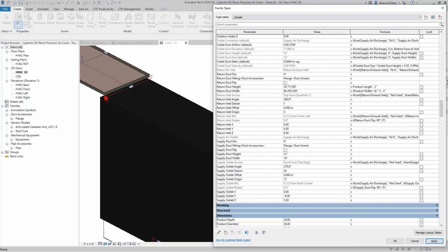So it's holding the wrong corner. My guess of datum 1 was wrong. So I'm just going to come back here and take a look and say, well, the other one that I want is quadrant 2. I'm pretty sure that's the one that I want. Hit apply. And actually, I knew it was quadrant 2 right from the start, so I could have just started with that, but I wanted to show that if you get it wrong and you hit apply and you get at least your anchor point correct, it'll position it in a way that you can go, okay, I put in the wrong dimension or the wrong quadrant, and now I've got it in the right position. But this moves it in any face to any position.